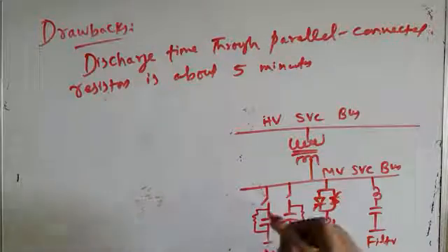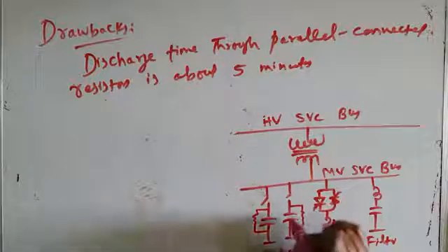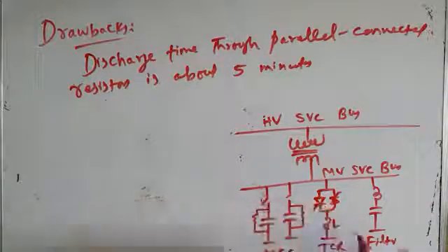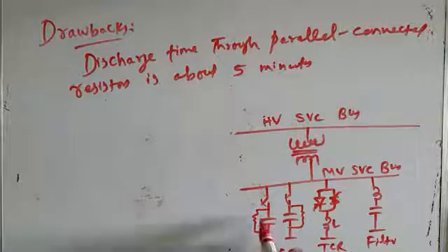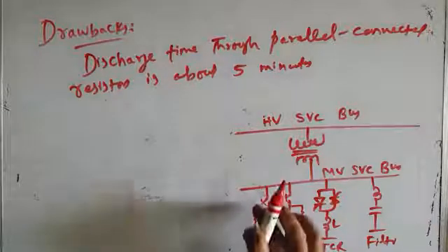But during this period, if operation of the TSC is required, you may have to close the capacitor banks before they have discharged completely. If they are closed with some trapped energy still in them, it results in high current and transient switching that may damage the capacitor banks. To avoid that, we want fast discharge when they are de-energized.